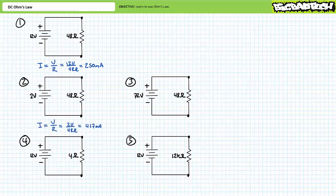Our second problem also features a 48 ohm resistor, only this time it's experiencing a much smaller 2 volt drop across it. We're being asked to solve for current through it. Current is voltage over resistance. An application of Ohm's Law demonstrates 2 volts over 48 ohms yields 41.7 milliamperes of current. Although we're employing the same resistance, this circuit experiences substantially smaller current because the voltage differential across it is much smaller.